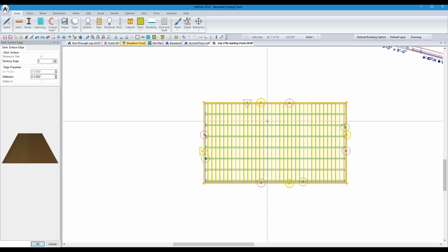We're going to automatically try and run the joist across the shortest distance, which is just common sense, but that's not necessarily the way you're going to want it, because maybe you want to split it into multiple pieces, that sort of thing. So as we've drawn this as a large polygon, of course, we're running the joist all the way across, and we're running the decking all the way down.